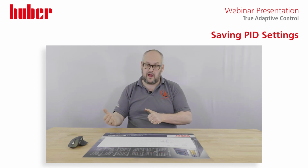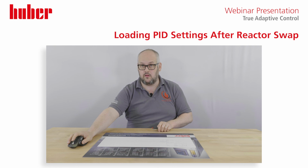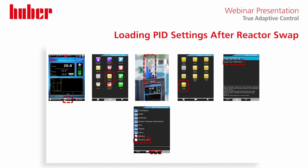So when you swap your reactor system out to an alternative reactor, you can just upload your settings by, again, inserting your USB stick, going to system settings, and in this case choosing load from USB stick, and then we can pick the reactor system that we're looking for.